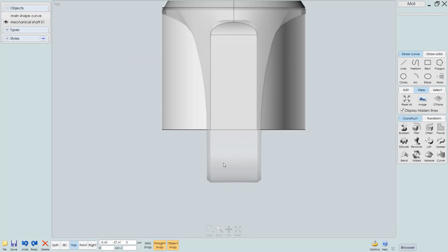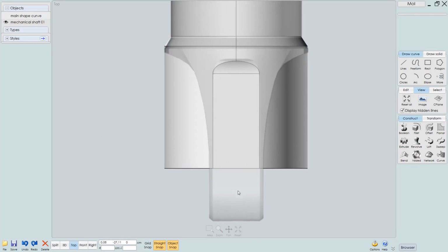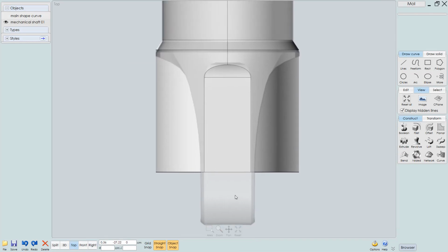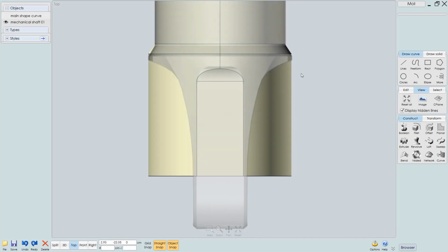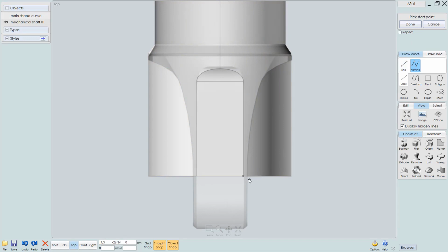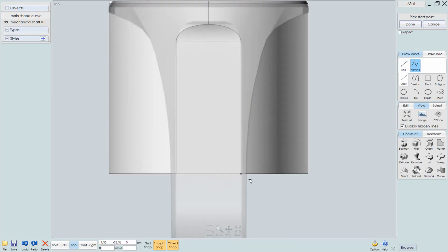Delete these parts. Let's check this in the top view, and I think that looks a little bit better. So let's create this cutout here. I'm using a polyline again, and let's start maybe here and create the next point here, but I want to make sure I'm staying parallel, and you do that if you have straight snap switched on, and you can see that light gray line.